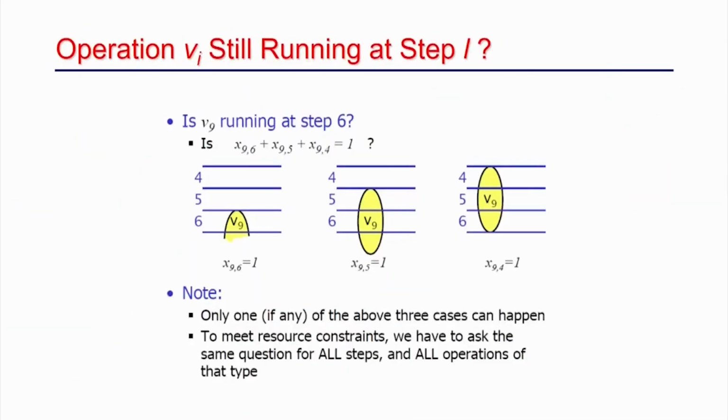If you think about time step 6, some operation starts here, some operation started early and is continuing in this time step, or some operation started much earlier and is going to finish here. So, all these 3 are active in this particular time step. So, I need at least 3 multipliers to execute these 3 operations. If this is the scenario, say this is V1, this is V2, this is V3, I need 3 multipliers to execute this in this time step.